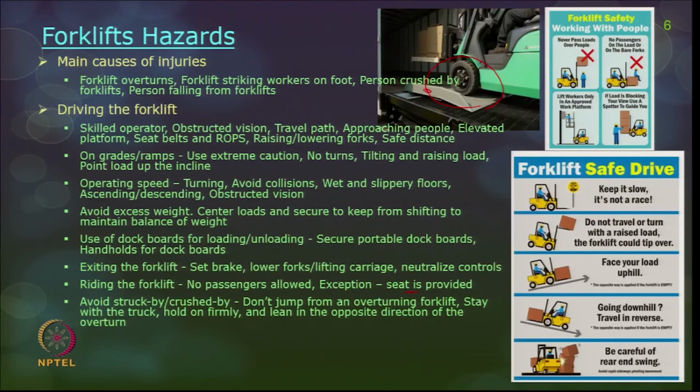Some of the posters are given here for forklift safety. Never pass loads over people. When there is people movement, you should not be moving the forklifts in that position. Pedestrians are not allowed to cross. There should be no crossing over of the pedestrian crossing and the forklift crossing. No passengers on the load or even on the bare forklift, and lift workers only in an approved work platform. So, this we have discussed earlier also.